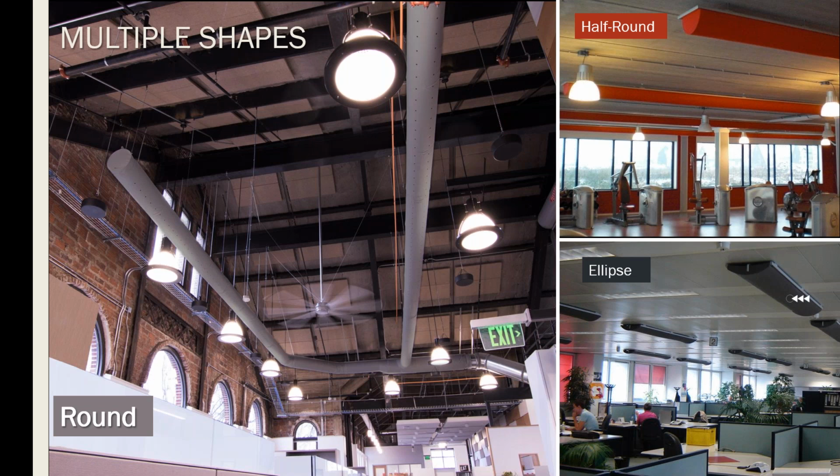That's the top right-hand corner picture. Half round can be suspended just below the ceiling with threaded rod or with cable drops, or they can be surface mounted to any finished ceiling. They can also be vertically suspended on columns or walls to act as displacement ventilation.